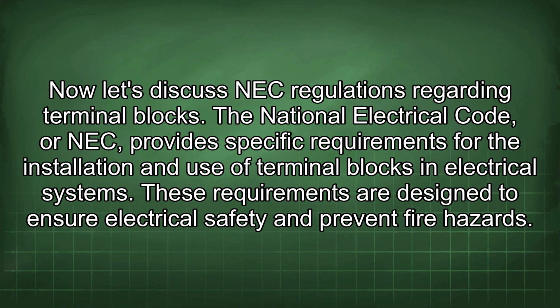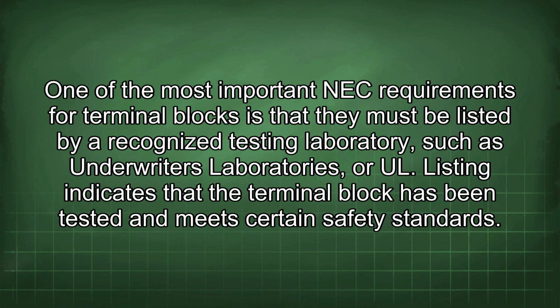Now let's discuss NEC regulations regarding terminal blocks. The National Electrical Code, or NEC, provides specific requirements for the installation and use of terminal blocks in electrical systems. These requirements are designed to ensure electrical safety and prevent fire hazards. One of the most important NEC requirements for terminal blocks is that they must be listed by a recognized testing laboratory, such as Underwriters Laboratories, or UL. Listing indicates that the terminal block has been tested and meets certain safety standards.